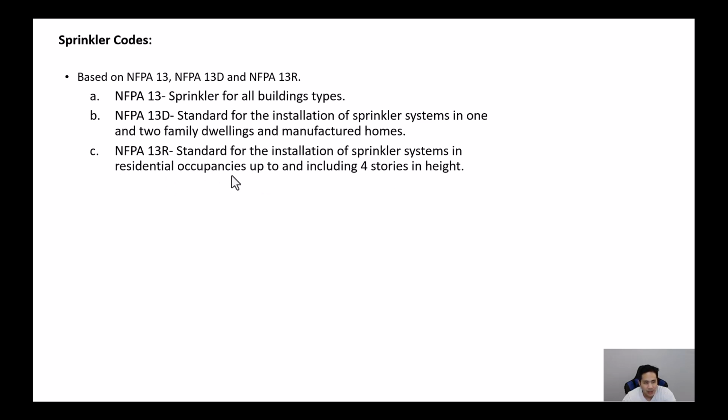So not just the 3 and up, but also 1 and 2. But the 1 and 2 can actually follow this code as well, NFPA 13D. And the requirements for this are a little bit less than 13R. So if you can use the less strict code, then it's sometimes better just to use that code.